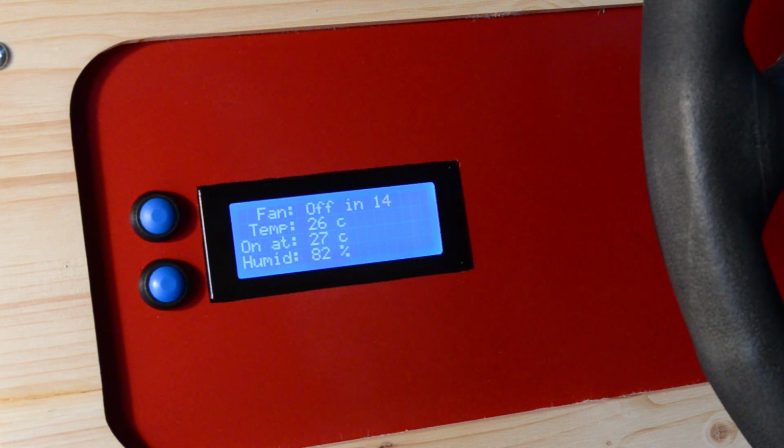So before, I had a simple rocker switch in the dashboard to turn on or off the 230 volts AC, but that was causing me problems because that AC wire was running alongside my video wires down to the PC, and it caused a flicker in my video, and sometimes my USBs would go down. So there you saw the timer expired and the fan is now off. So that gave it time to settle the temperature down. But now let me show you what it looks like inside.